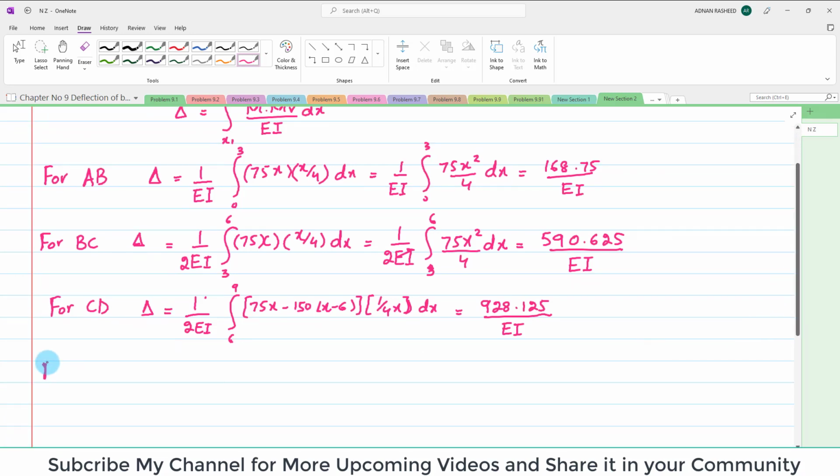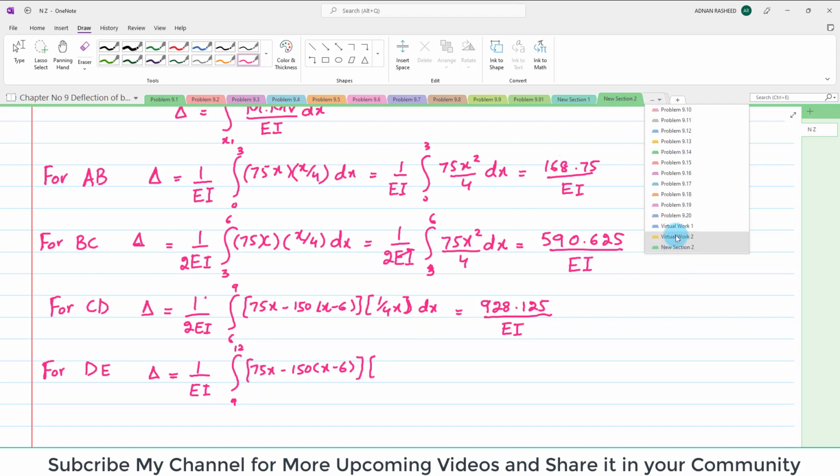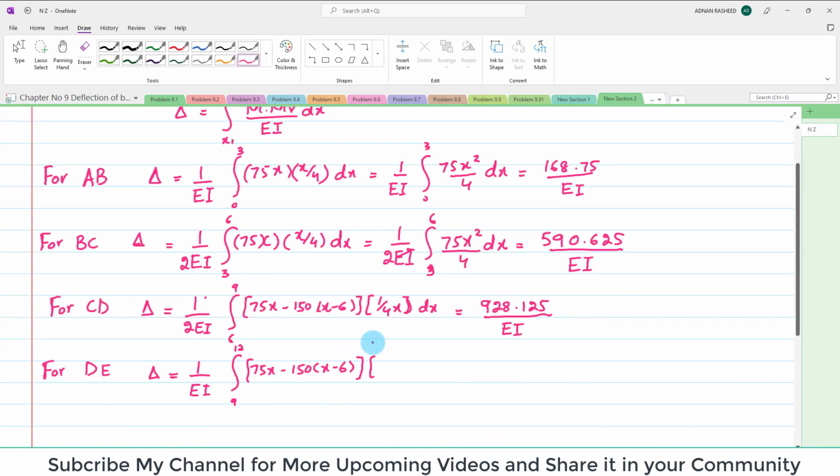Now for D to E, the deflection will be equal to, again here from D to E, this is EI only. So we will put EI only, 1 over EI, integral of 9 to 12. The moment equation was the same, 75x minus 150 into x minus 6, clear, and mv was changed, and mv was 9 minus 3 over 4x, 9 minus 3 over 4 into x into dx. When you multiply it and simplify it, you will get 506.25 over EI. Now you have all the values. You can find out the deflection at point E.